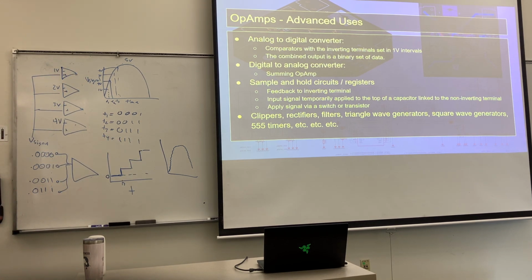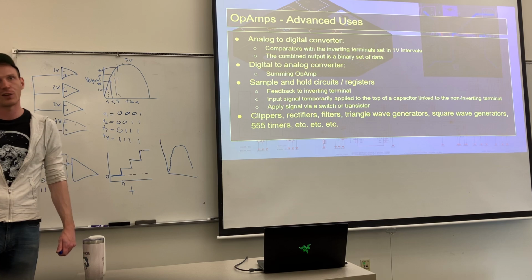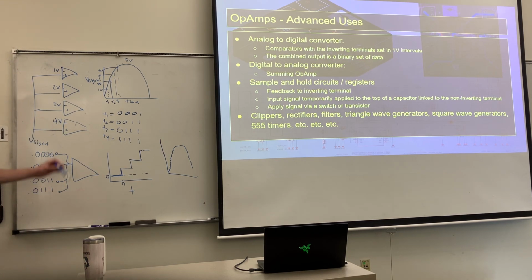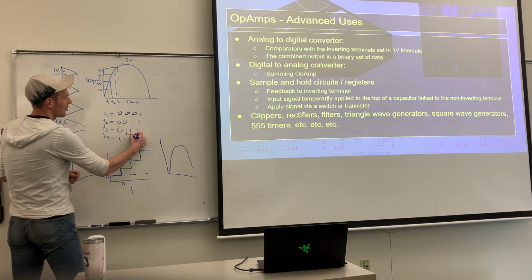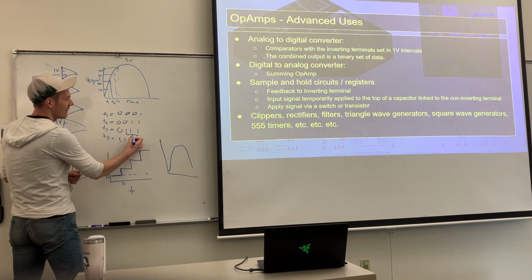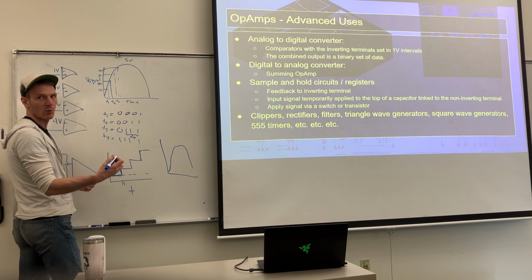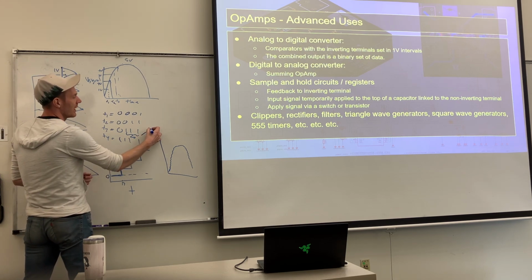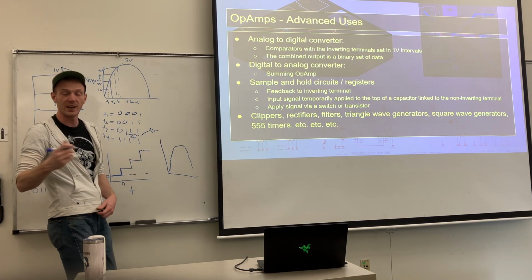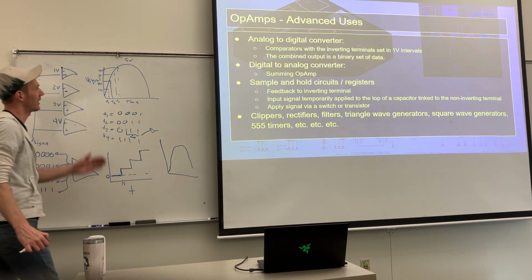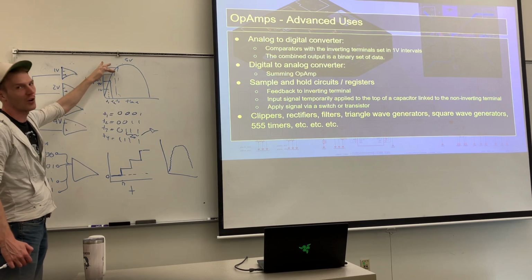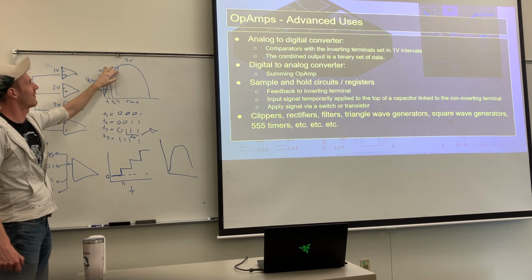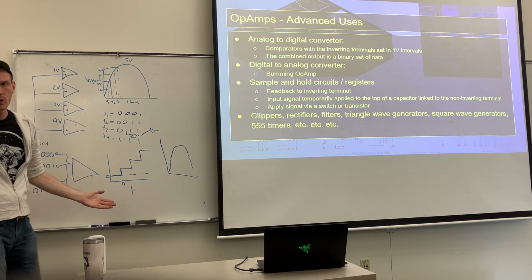And using some system, you might have some use of this information depending on what you're trying to do. You can have that drive some sort of output, do whatever you want. You can use Boolean logic; we talked briefly about OR gates, AND gates, NOR gates. Use those to say, okay, once these 3 are 1s, I have an AND gate, so all of them have to be 1s for it to be 1. And as soon as all 3 are 1, it outputs a 1. And now we do work. So if I have a sine wave input and want to turn on a fan, an LED, whatever, at 3 volts, this is the way to do that.